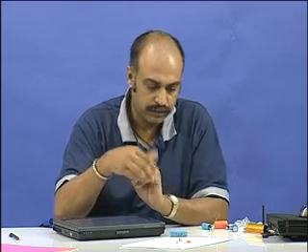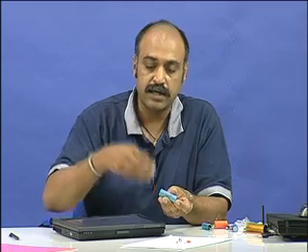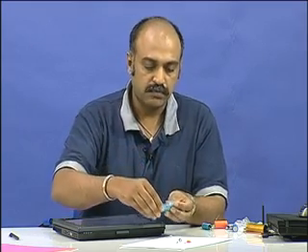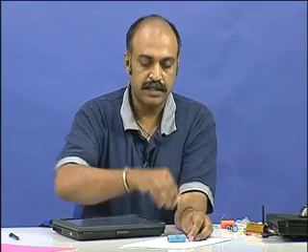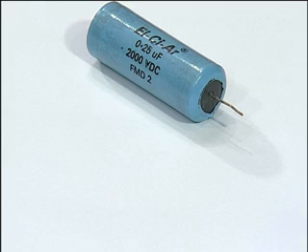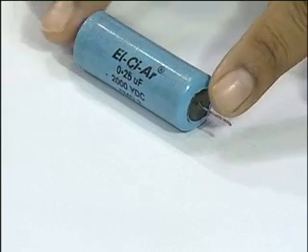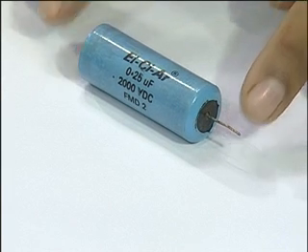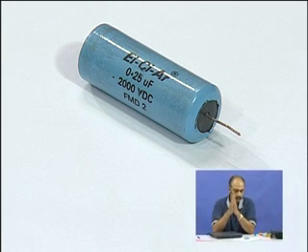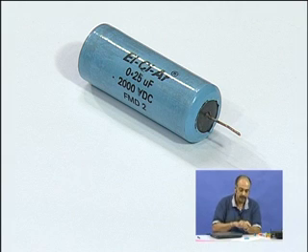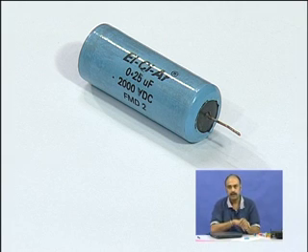Okay. So, an ideal capacitor is not lossless, it has some loss in it due to these practical limitations. So, due to that the size also will vary. As the currents in the capacitor increase, the sizes will also go up because the ESR is going to dissipate that. Now, here is another non-polarized capacitor which can handle much higher current than the ones you just saw, which means that higher current carrying capacitors should have lower equivalent series resistance or ESR. So, this is one such non-polarized capacitor normally used for snubber applications.